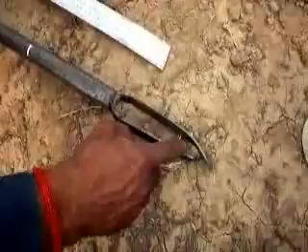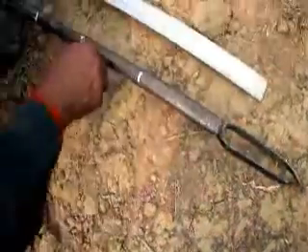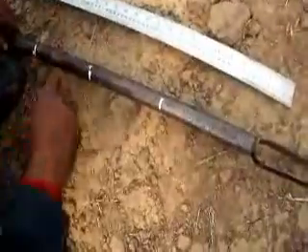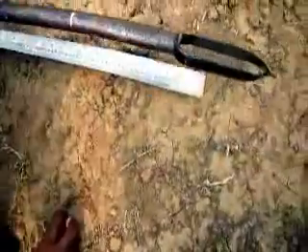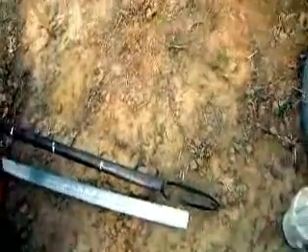So these are the points. If we insert this auger inside the soil, we will get samples from 30, 45 and 60 centimeter, and collect the sample to compare with the soil moisture we have measured from the tensiometer and FDR method. So let us take the samples.